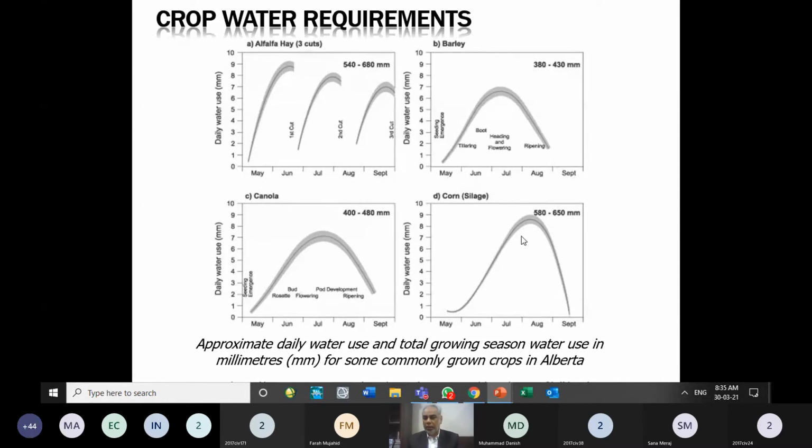But if there are orchards, because they are multi-year crops, they don't start in a certain month. So initially they will have a similar pattern, but then for a few years they will have constant water requirements till the death of that orchard field, till we cut those orchards or gardens. So they can have multi-year water requirement. But usually our crops are seasonal crops, 3-month crops, 4-month crops. Few crops extend for a year, like perennial crops; sugarcane can be considered a perennial crop.